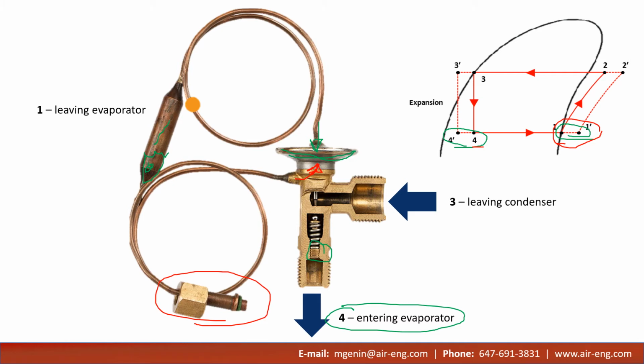Nowadays, many systems are moving towards an electronic expansion valve where the suction pressure and suction temperature are measured with electronic devices, and then the valve is controlled with an electronic solenoid motor. This has a pre-programmed curve or dome for this refrigerant, and the computer automatically determines how much superheat there is and if we need to meter in more or less refrigerant.